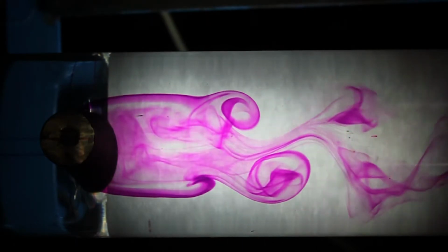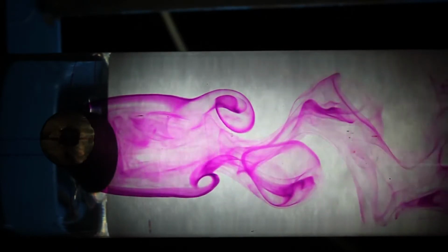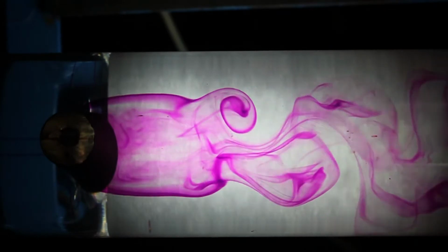How do I know that it is turbulent? Because eddies are formed, vortices are shed. The very fact that there is a presence of vortex itself means that the flow is turbulent. Now let us take up a Reynolds number of 10,000. This is a trapezoid. You can see that the eddies are formed and they are shed at a faster rate than what you were seeing for laminar flow. This is also a pipe, this is a trapezoid, and the flow is getting separated at this tip, and the pipe Reynolds number is 10,000.